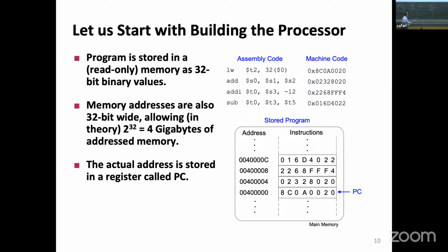Okay. Now, if you end up coming to the control part, what happens is we end up looking at a number of things that we are receiving from the upper part. So this is where I'm trying to explain what we are doing. Let me take my cheat sheet so I stay consistent. So for an R-type, we have to see what the operation is. And so these are the 6 bits of operation which I pick as the first things. And if they are 0, 0, 0, 0, 0, 0, I know that I'm doing an R-type. And then there are some numbers that I want to set. Well, there is the reg write. This one should be 1 whenever I'm doing an R-type operation.